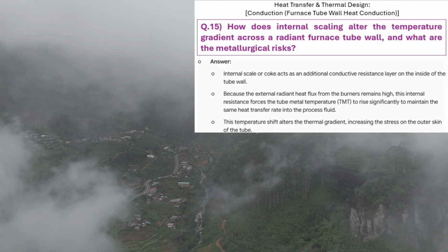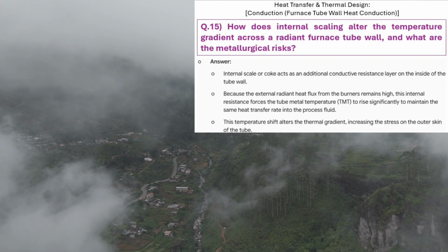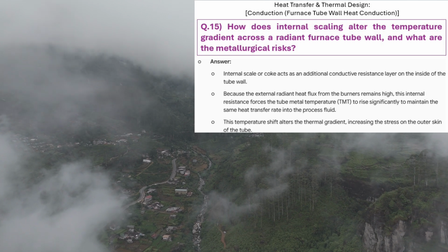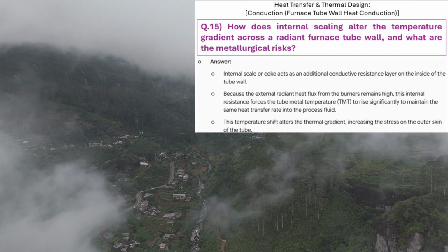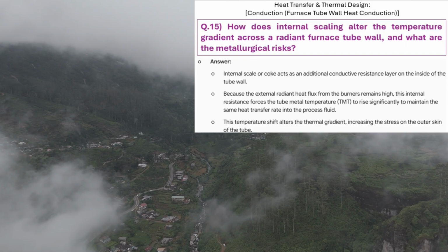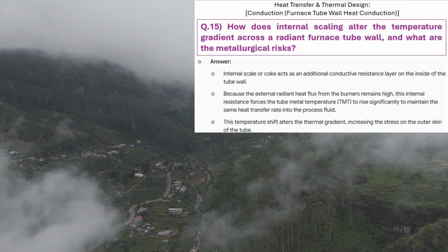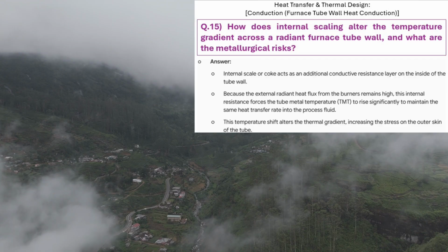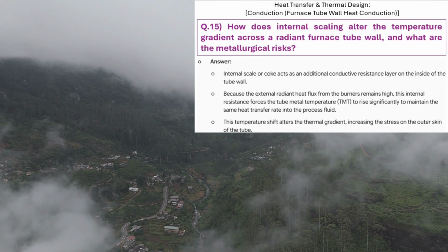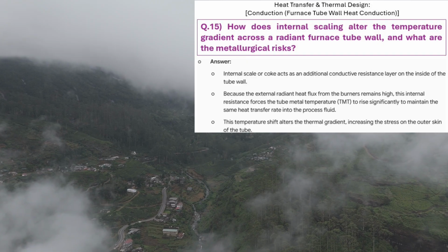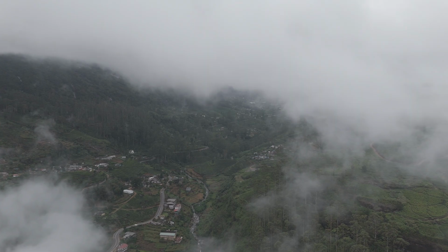To physically push the required thermal energy through that resistive layer, the outer tube skin temperature must be aggressively driven from 540 degrees up to an extreme 630 degrees Celsius. That 90-degree spike pushes the high alloy seal past its creep threshold. Yes. Sustained stress actively accelerates structural creep deformation, the permanent metallurgical elongation and physical thinning of the steel. This localized thinning leads directly to a catastrophic high-pressure split tube fire inside the radiant box.